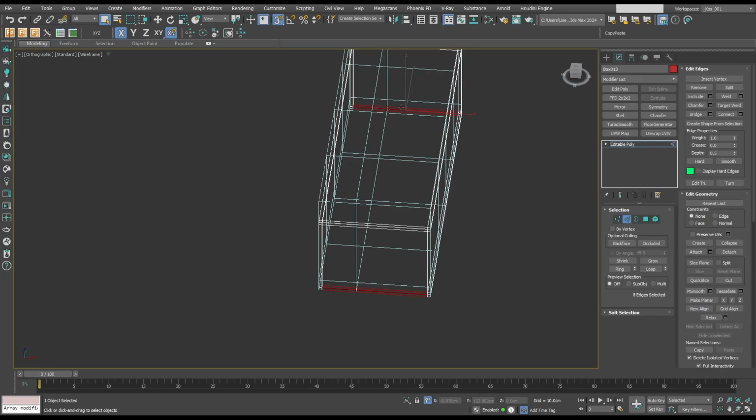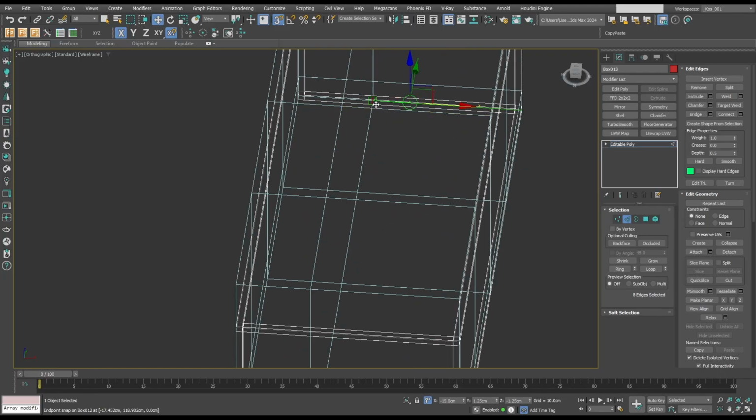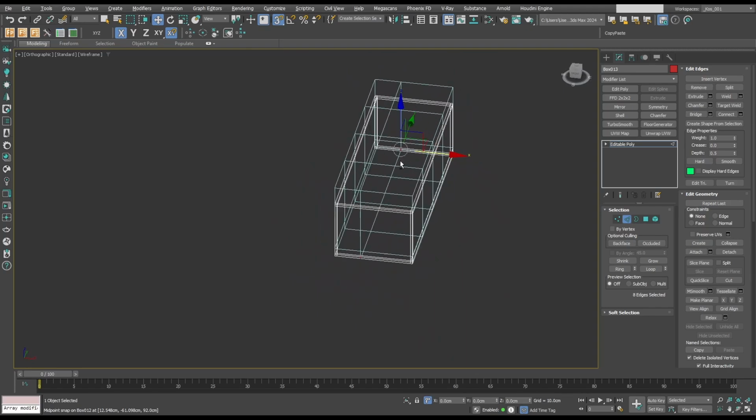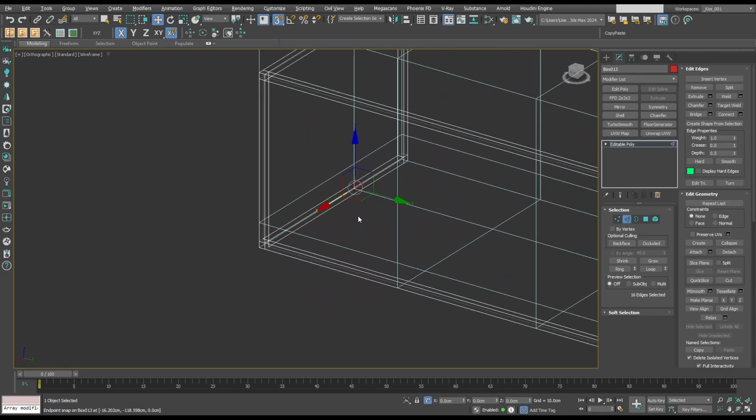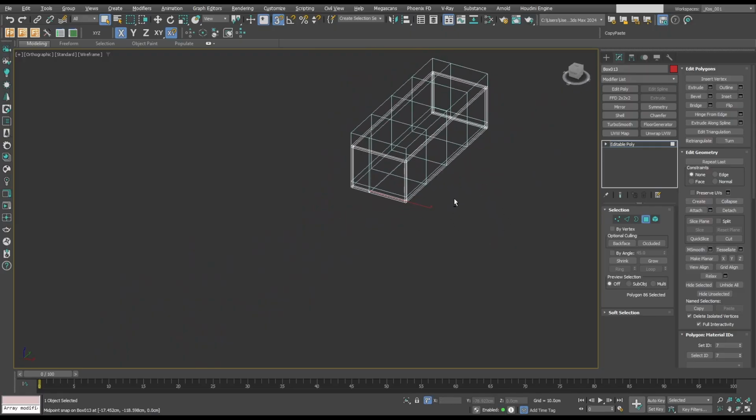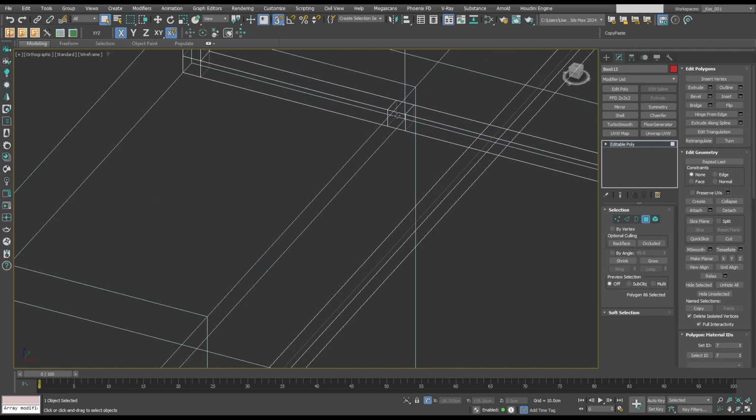I select the edges, connect them to create one edge loop, snap them, and by chamfer I can give the amount of 1.25 without any segments, and this is our division from which we can bridge the faces to create our connection.